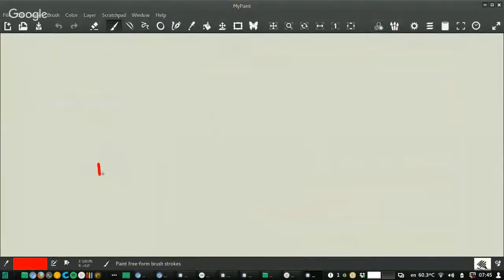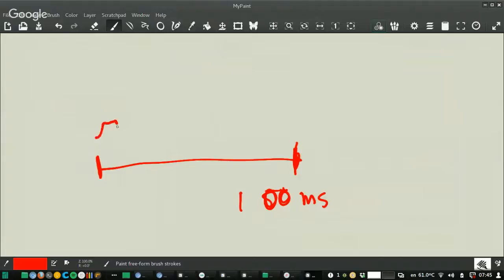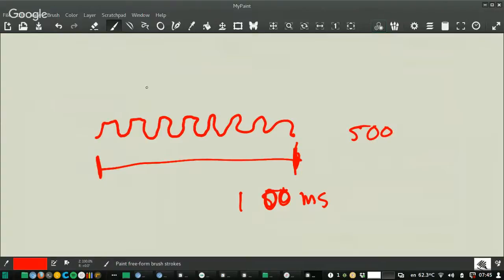So I trigger the counter. So I wait like say 500 or 100 milliseconds. And in this time, how many times can I charge and discharge and charge and discharge this thing I'm doing? And you will get a number like 500 times. And when you put your finger, maybe it's 2,000 times. Okay, because you can do it faster. You can charge and discharge it faster because your finger is coupling with this. So this is the approach you are using.